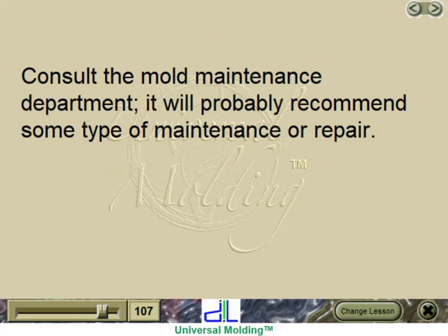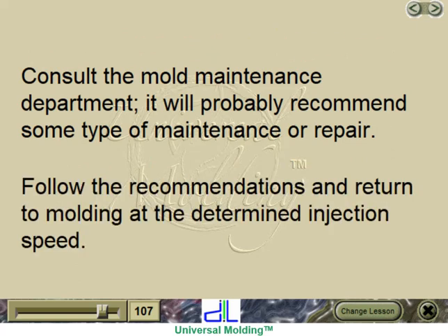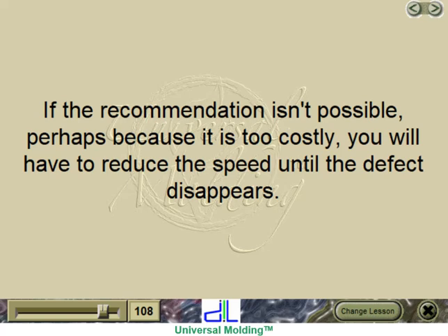Consult the mold maintenance department. It will probably recommend some type of maintenance or repair. Follow the recommendations and return to molding at the determined injection speed. If the recommendation isn't possible, perhaps because it is too costly, you will have to reduce the speed until the defect disappears.